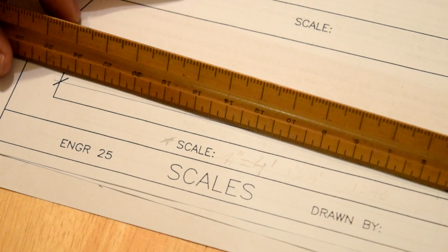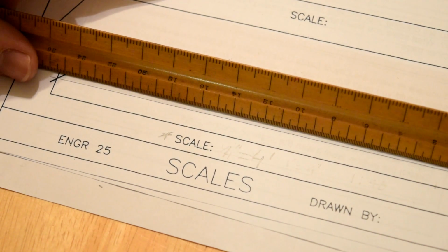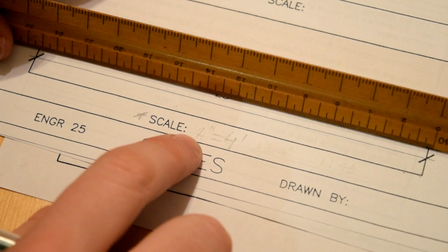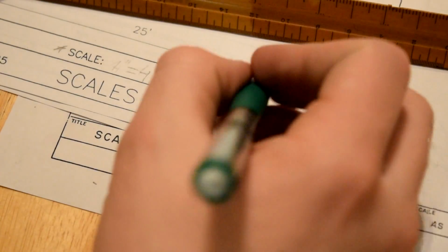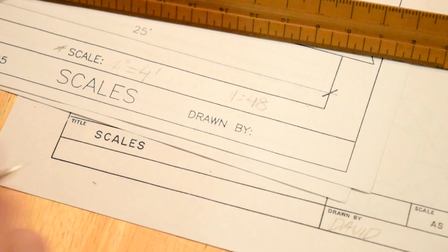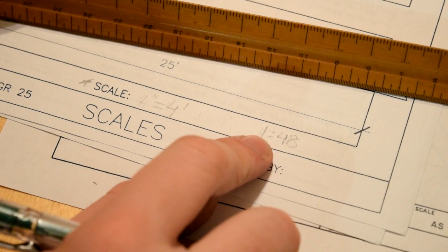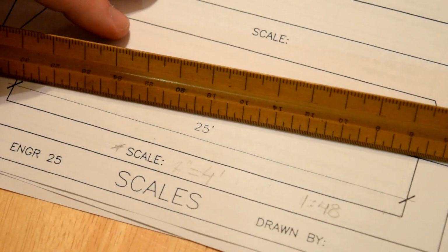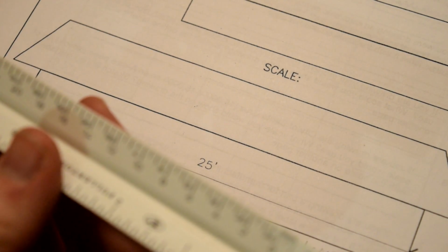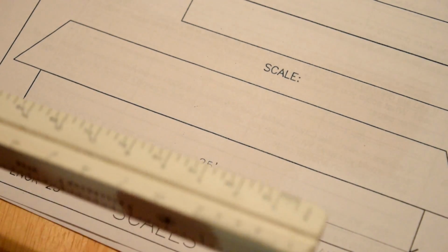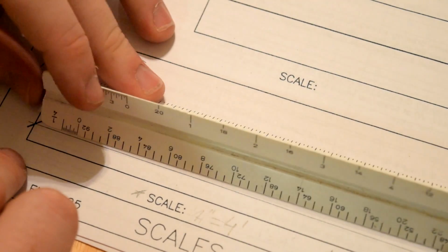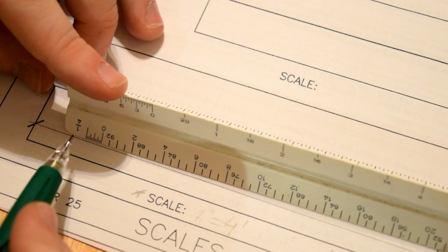Another scale that I know would work is actually the same size. If we convert this really quick, 4 times 12 is 48, so we know that this scale is a size of 1 to 48. So everything we draw on paper is 1/48 the size it is in reality. Another scale that actually has that same size is the 1/4 inch scale on the architects. So I'm using my 1/4 scale.